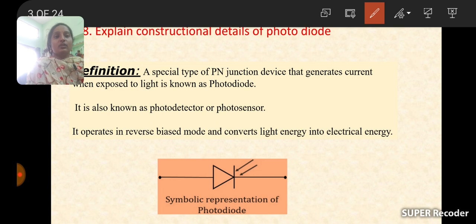Coming to the uni-junction transistor, it consists of only one junction, made between the emitter as well as the base. In a UJT, there is one n-type semiconductor bar into which a heavily doped p-type bar is diffused.